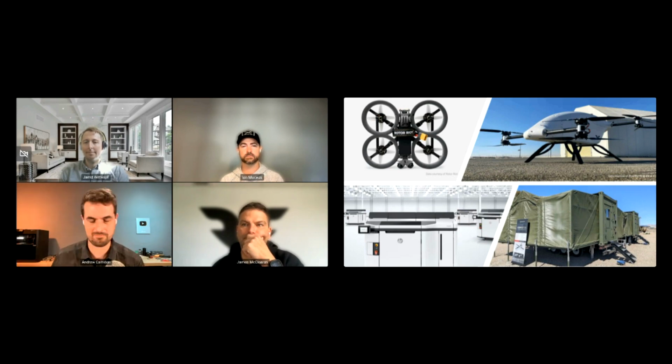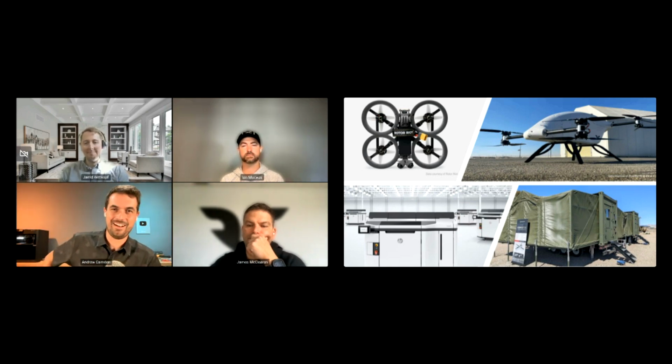And in this case that we're looking at now, there's a CNC feature that adds a ton of machine time, and we just realized, well, wait, what if that was a separate plastic piece because it doesn't need the aluminum strength, right? Maybe we'll do it with additive.